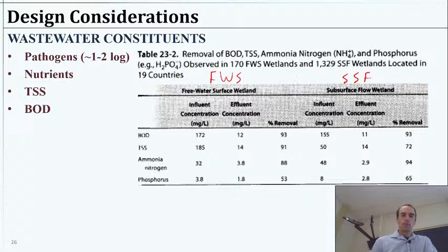So for these observations, we can see the influent on the left column and the effluent on the right column. So we went from 170 to 12 in terms of BOD on this particular example. That's great, right? That's a significant reduction. And when we're anywhere kind of close to the amount of oxygen saturation, there's a good chance whatever stream or something can handle that, especially if it's not 100% the wastewater, right? So if we're like 100 BOD, we're probably in trouble. If we're not so close to that, we're probably doing all right.